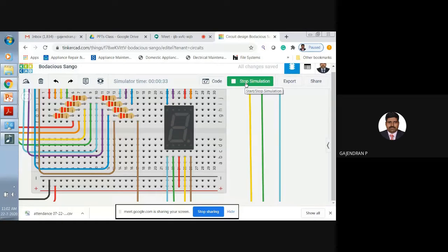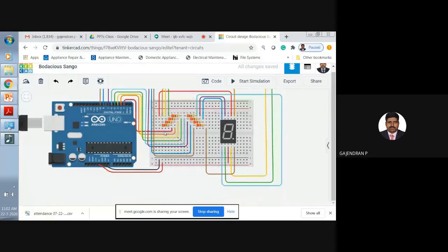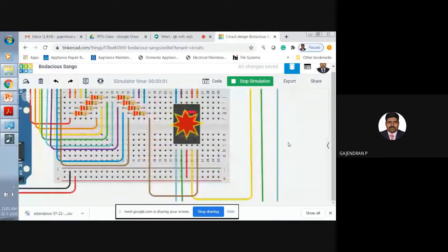See, what are all the mistakes you people will make? Instead of connecting the resistor in series, you will give all the connections perfectly, but you will connect both the input and output terminals to the same node. If I give it like this and start simulate, please observe, what does this indication represent?